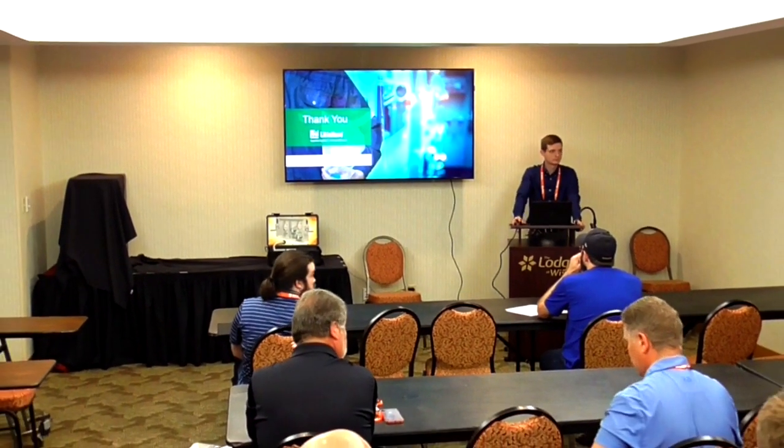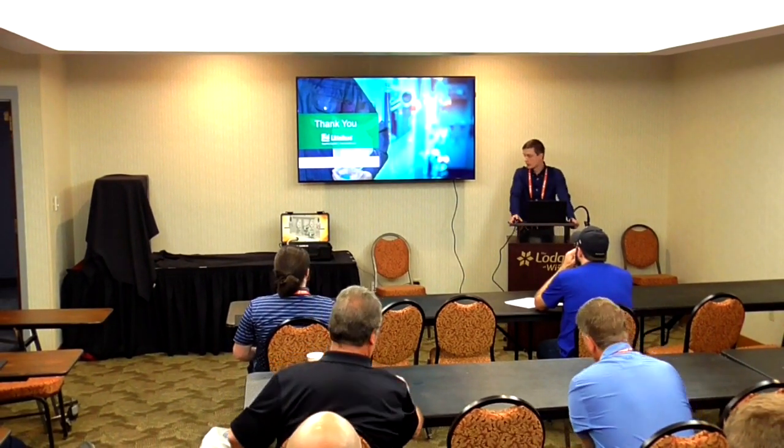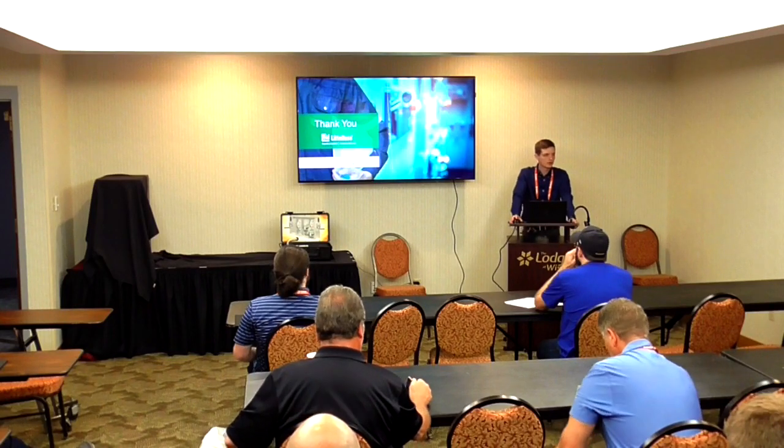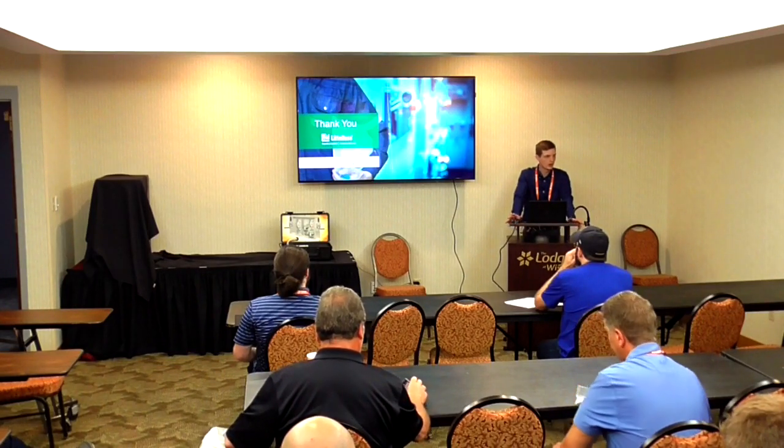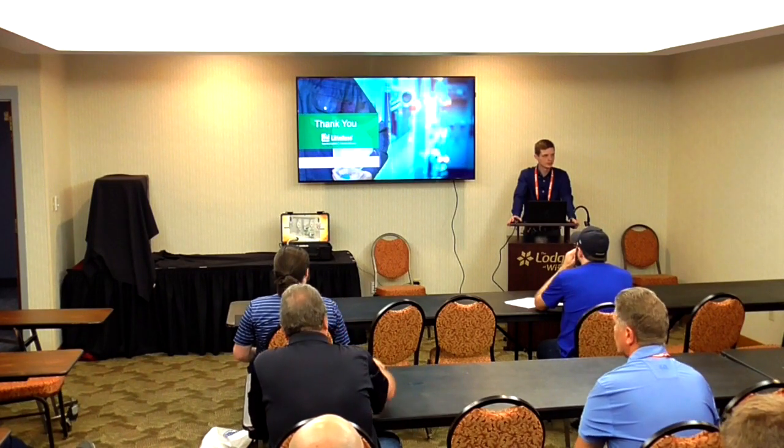For the arc flash relays, what's the maintenance like for that? What's the recommended maintenance? You typically don't have to perform any maintenance unless you notice that the unit itself becomes faulty. They typically last 10 years, 15 years without any incident.